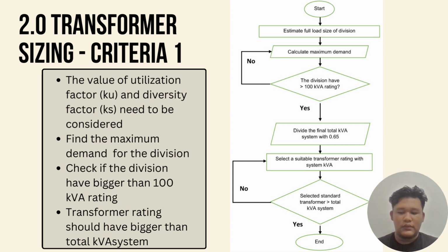After that, select the suitable transformer rating with system kVA. And then the selected standard transformer should be over the total kVA system. And if it's not, the transformer is selected again with system kVA. And if it's yes, the transformer can be used.